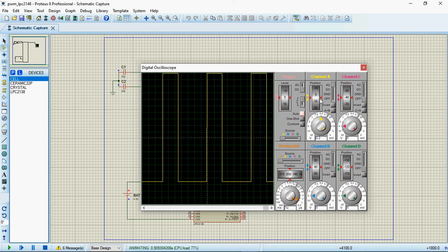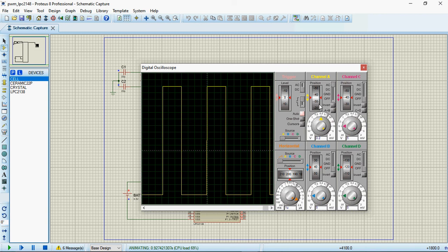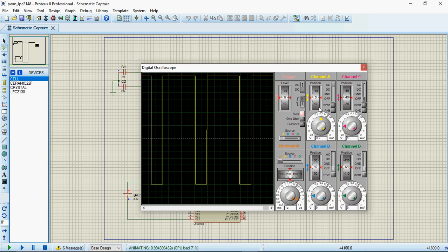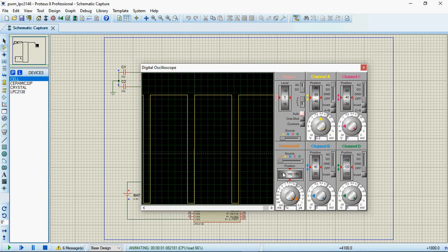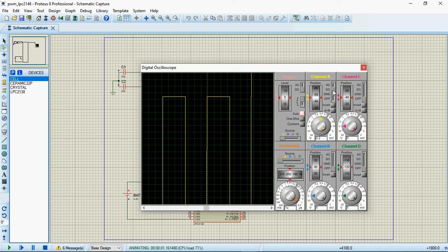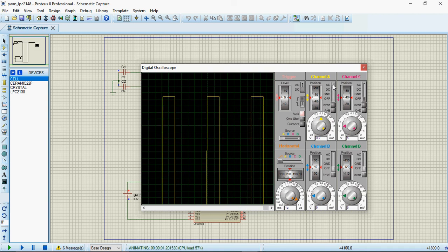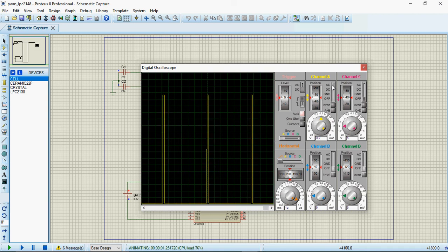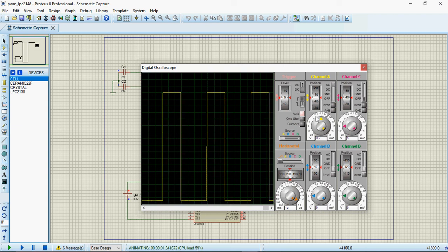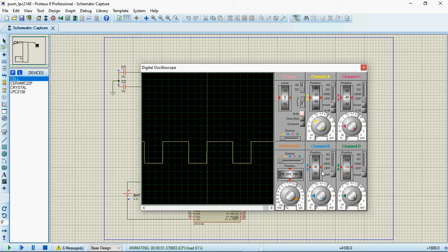This is the position which you can use for making the adjustment along the Y axis, and along the X axis you can use this to make the adjustments. Hope this made sense. Understand, AC mode you have to keep, and here the trigger should be DC, this is 0, and that's all you have. So hope you try to get this output. That's all fine.